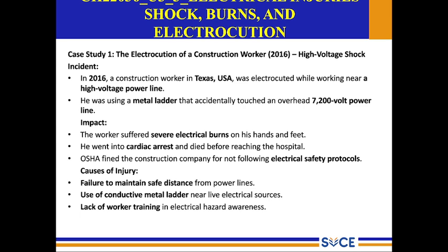The next is use of a conductive metal ladder near live electrical sources. Where electrical wire is nearby, we should not use any kind of metal ladder. We should use only wooden, non-conductive structures.